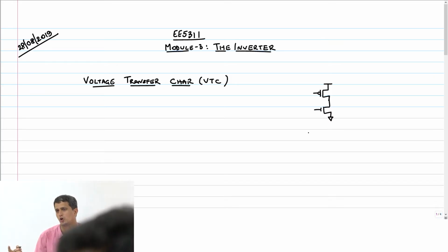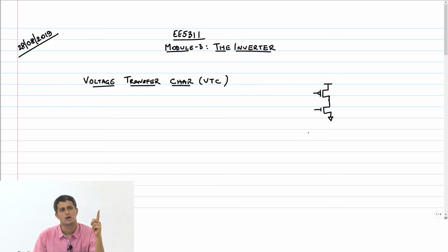We looked at all four combinations and concluded that PMOS can be used only to charge a capacitor, and NMOS can be used only to discharge a capacitor, so that the output voltage swing is rail to rail. Therefore our CMOS inverter, complementary metal oxide semiconductor inverter, is made of both NMOS and PMOS. There are alternate ways of making these inverters, which you will see in the tutorial.